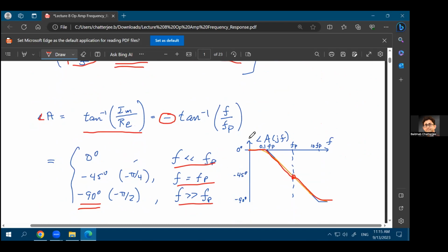The other day. So what you do is that you have one amplifier connect the output to the second amplifier. The second amplifier will have an input capacitance. So that's how you'll always have this parasitic capacitance C0, and that C0 along with your R0 will provide this low-pass filter response. Question? Is that C0 the value of that capacitance?